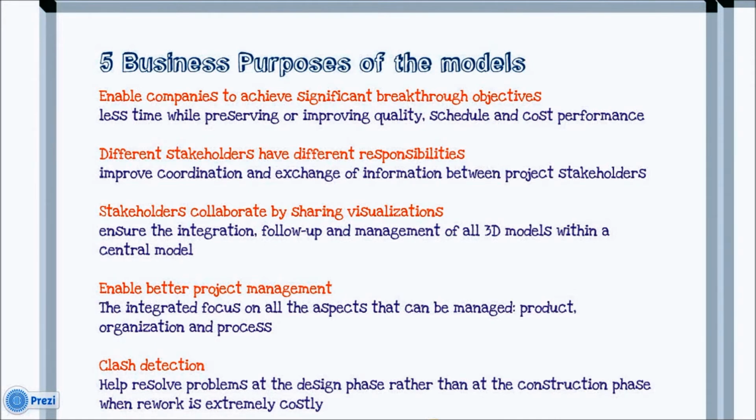Finally, VDC helps clash detection. VDC links all the models and analyzes them to detect clashes. It helps resolve problems at the design phase rather than at the construction phase when rework is extremely costly.